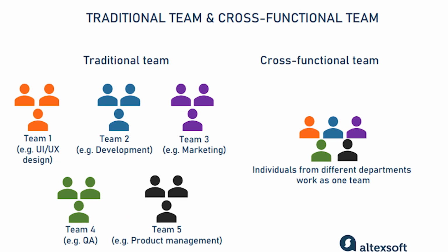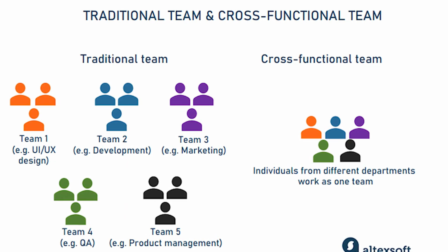So that brings another important context, what are the industry challenges as of now. The first and foremost challenge is with respect to the effective use of cross-functionality. Many times it is observed that when we are making the process flow chart, process FMEA or the control plan, there are different people doing things and there is no relationship or linkage between all that. So these are 3 different documents and not interrelated, where the output of one is the input of another. It's a big challenge which is being seen in the industry.